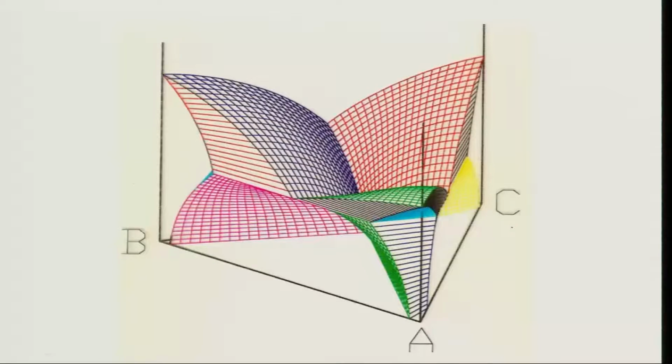Things will be much clearer here. This is a very good picture. You can see here the binary eutectic between BA, the binary eutectic between AC, and the binary eutectic between CA. The ternary one is basically curving down here, correct. So, if I draw a horizontal plane at the ternary temperature, the 3 points will be the 4-phase equilibrium plane, correct.